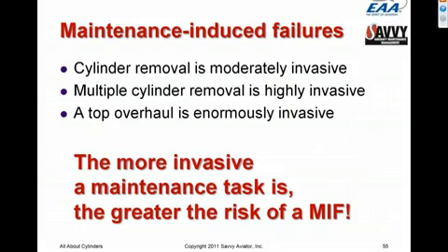Cylinder removal is a moderately invasive procedure, but multiple cylinder removal is highly invasive and, with alarming frequency, will set up the scenario for an engine failure. So we need to be very careful about that. My advice is that if you need to remove multiple cylinders from your engine, you take the airplane to an engine shop and let an engine expert work on it. There's just too much potential for maintenance-induced failures when these things are done in the field. That's my own opinion on this.